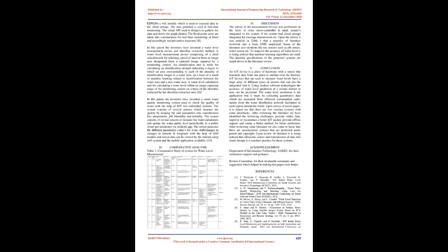7. The last paper reviewed was a water level detection IoT platform based on wireless sensor network 8. In the proposed system the WSN, wireless sensor network, has been used. The proposed system works on NodeMCU along with the HC-SR04 sensor, a distance measurement sensor, and ESP8266, a Wi-Fi module which is used to transmit data to the cloud storage.